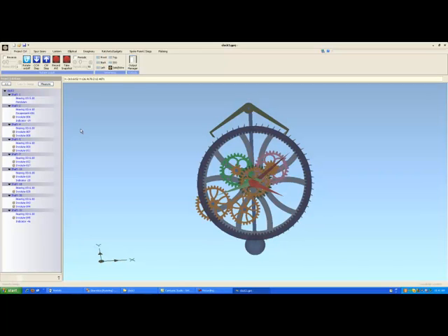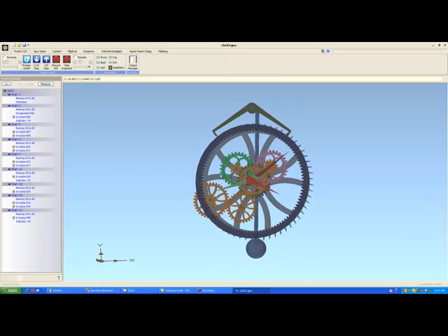If we look at the bearing ODs, you'll see that they're defaulted at the moment to the same size as the shafts which hold your gears. This would rarely be the case unless you don't intend to use bearings in your plate, and I do recommend if you're going to build a clock that you put bearings in your plates.